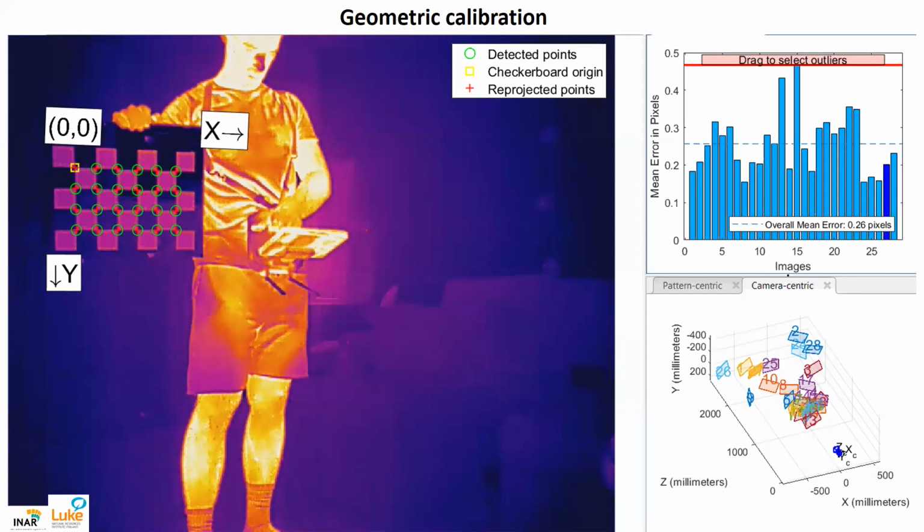No, I have used this option in order to map the thermal images on the point cloud, because it's my research line, and I use this option of the camera to correct the geometric distortion of the thermal images. Maybe it could be a good option. Okay, well, this is a kind of indirect correction. I imagine it probably works if you have tested it, but I just wanted to do it in the simplest possible way without any extra work, and it seems to work because I'm obtaining very reasonable lens distortion coefficients and camera intrinsic and extrinsic parameters this way. But it's just a pure imitation of an RGB camera. Okay. Thank you very much.